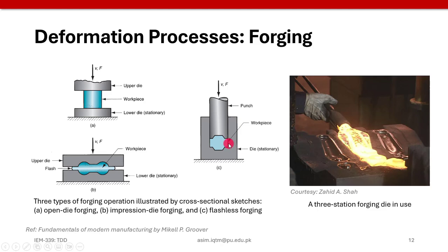But again, the material requirement going into this type of die is really important, because adding too little material to this type of die set would produce a faulty product, and excessive material would again produce a faulty product, because the excess material would not properly be able to close the die, and the size of the shape would be large if an excess amount of material is added into this type of die set.